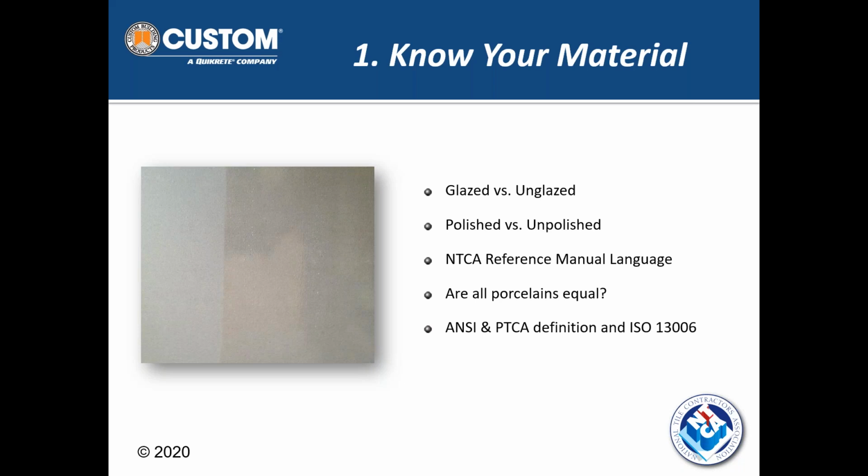What's going to happen when we grout it? Especially, like we've seen with stone, if you were to grout that material without pre-sealing it or using a grout release, which we'll talk about in a few minutes, I would tell you that's going to stain quite readily as well. These are all things that are very simple and easily addressed, but oftentimes they're simply overlooked for time, or just because maybe we never had a problem with unglazed, unpolished porcelain. Well, again, they're not all created equal.